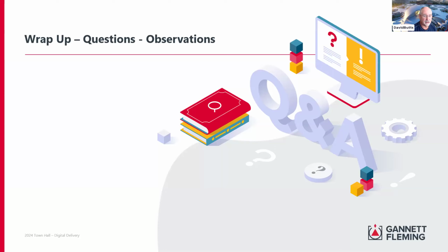And so as we started building out our new computers, all the Revit users get Civil 3D. They're actually using Civil 3D. We don't want them using plain AutoCAD, because you need to check the units and not only that, but the coordinate system, like North Carolina NAD 83. You want to make sure that you can actually access that, check it, and edit it to make sure that it's correct, so that when we link it in and we do shared coordinates, everything's working correctly and it's assigned the right coordinates.